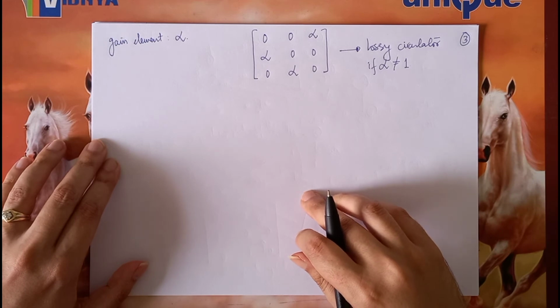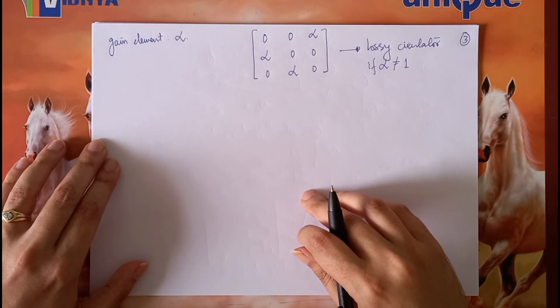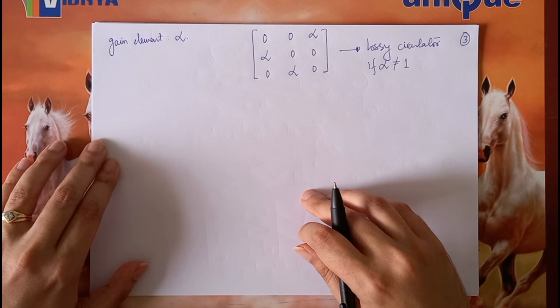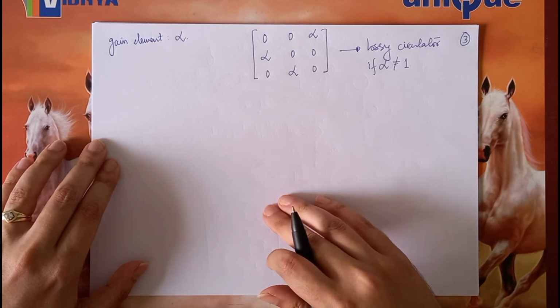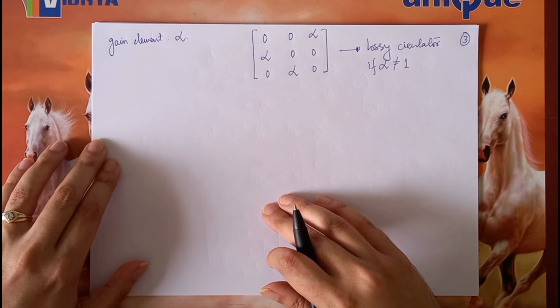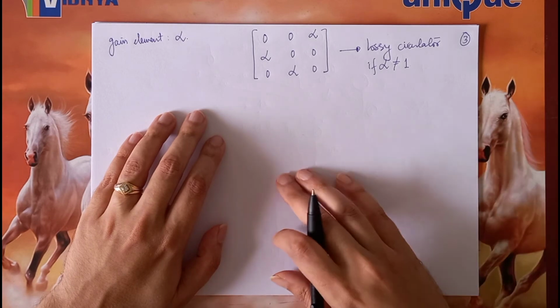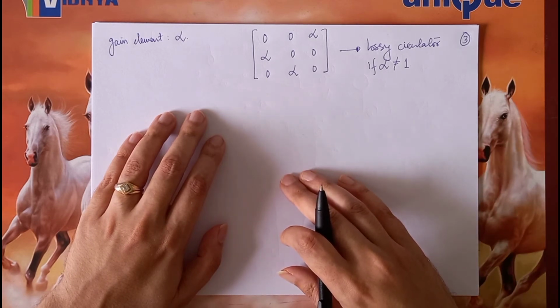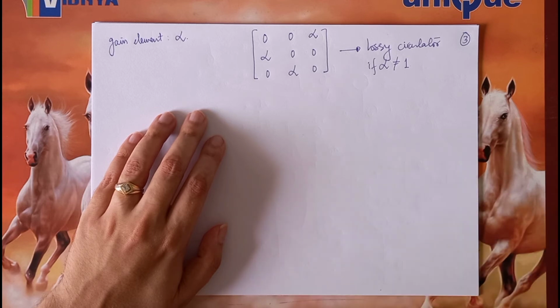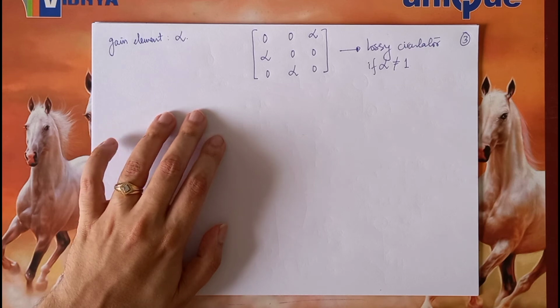We said this also in the previous lecture, that if you consider that there are two current carrying conductors, if the current is of equal magnitude in both the conductors with the same direction, then it is something like the even mode. If the current is the same in magnitude as the first conductor but is opposite in direction, then it is equivalent to the odd mode.